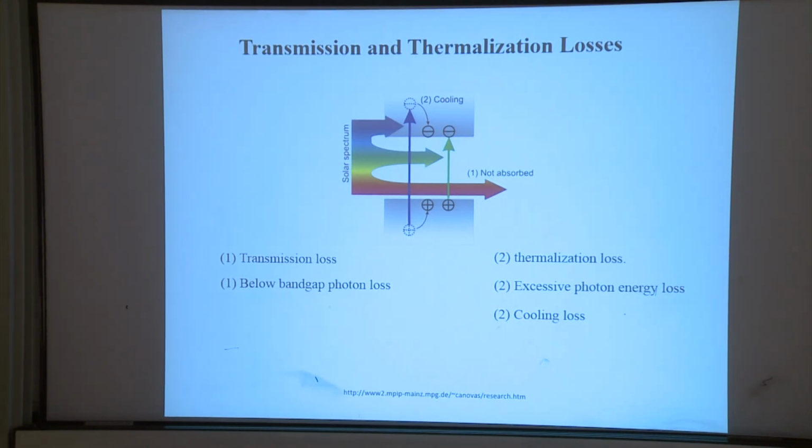So since we cannot choose the incident light from the sun, then how to maximize the solar cell efficiency? We choose a semiconductor material that best fits the green light or best fits the solar spectrum, right? But still, we cannot use everything because once we choose the band gap of semiconductor, there will be photons in the solar spectrum not absorbed by this semiconductor, like infrared or red light.